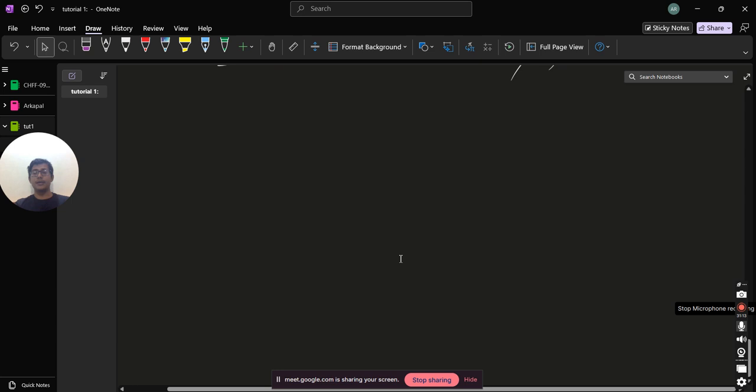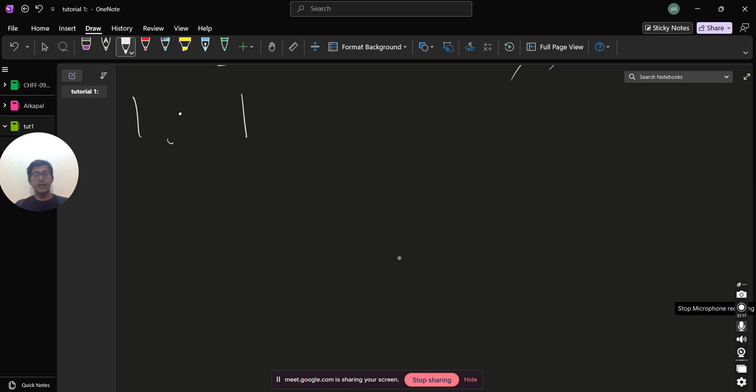So if you remember, at the center we have the rho and u, v and w. Now, this is the delta x, and the distance from the center to this part is nothing but delta x by 2. Now we will use the Taylor series expansion. We know the flux here, right? Because we know these values.